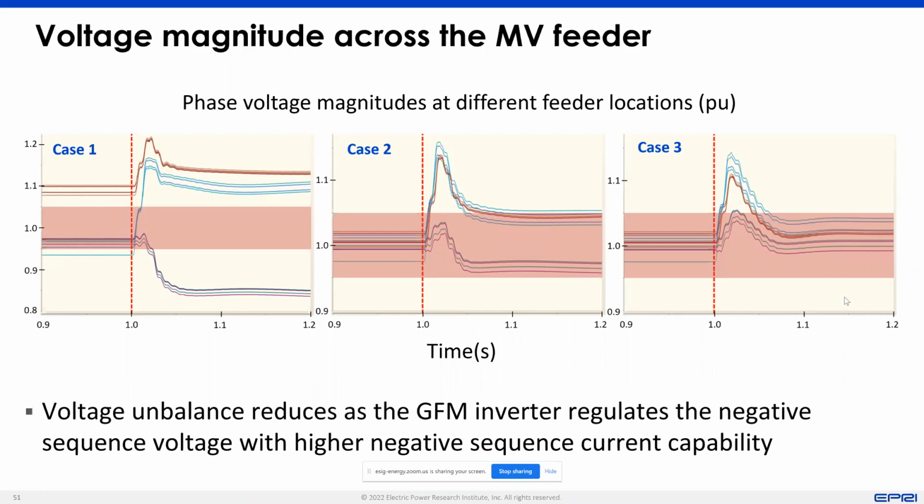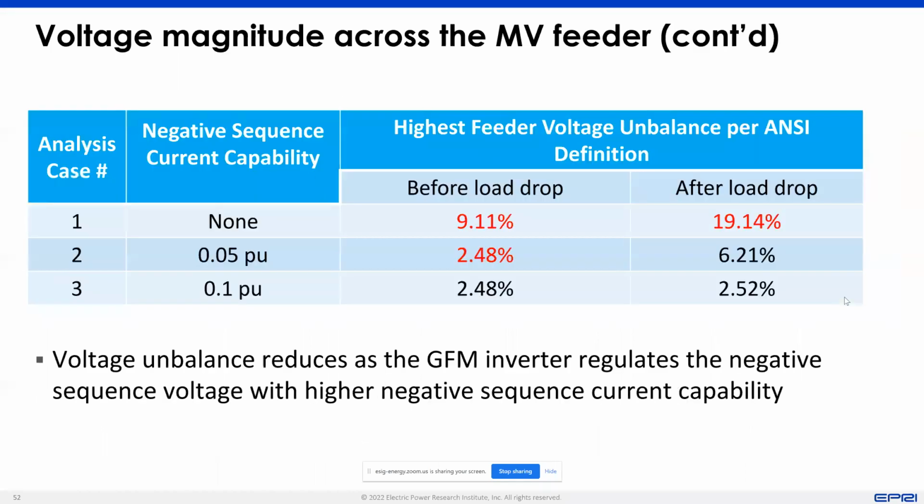What happens when the inverter was disconnected in the system? You are right. If this is a grid following inverter, it would have tripped due to 1547. We did not implement that trip mechanism here because first of all, this is grid forming, and for grid forming, we're not sure whether you need to enlarge that range of operation. And second of all, the goal of the study is mainly to look at how it affects the voltage imbalance, so the trip behavior will not affect the result much.